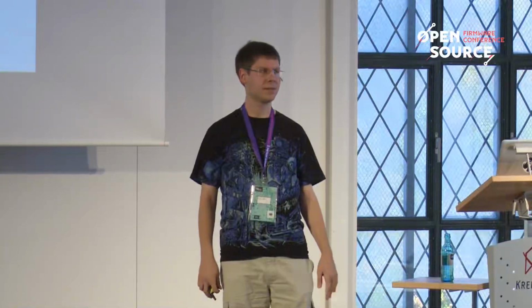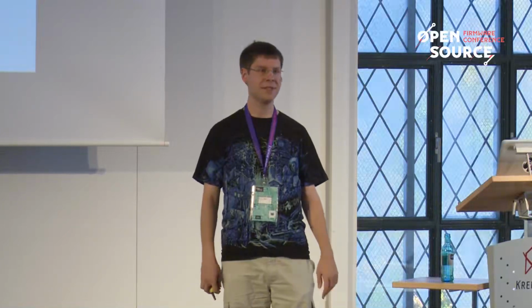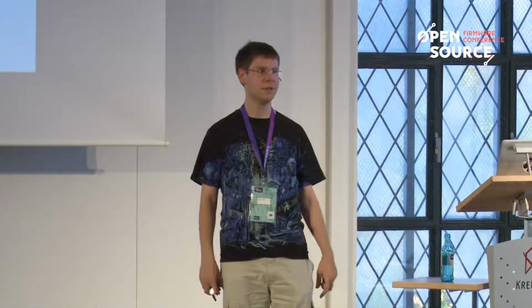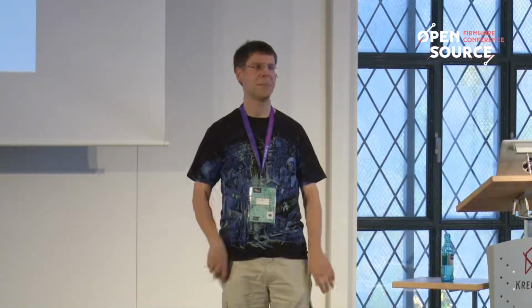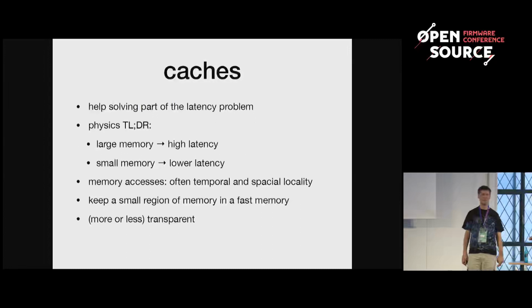So that's basically putting a gigabyte of SRAM on a computer, you basically can't afford that, or you try not to use that. I think there are rather big SRAM chips, like 64 megabytes or so, used, for example, in routers for the route tables, or part of the route tables. But those memories get really, really expensive.